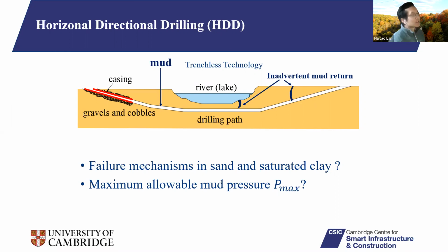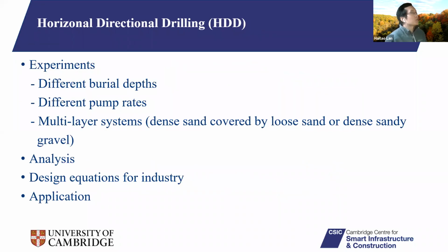Because I don't have the time to talk about all the details of my PhD research, today I will focus on some of the tests I carried out in sand. Actually, in sand, we also did a series of tests. We investigated 3 main factors to see how they influence the peak or maximum allowable mud pressure. So we investigated different burial depths, different pump rates, and multi-layer systems, that is a dense sand covered by loose sand or dense sandy gravel.